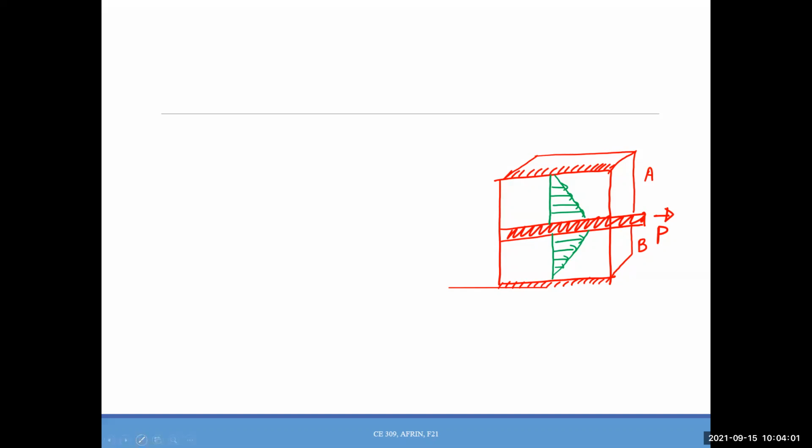And here, that was the kind of schematic diagram for this problem. Since this is fixed, what will be the velocity on top? Here, the velocity will be 0. And what is the velocity here? Do we know the velocity on top of this plate? Good, 6 millimeters per second. Again, the velocity is 0 here, and velocity here is 6 millimeters per second, right?